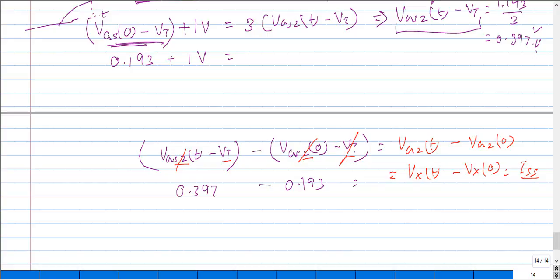And this quantity is basically assumed to be equal to the slew rate, and that is given by ISS divided by the capacitor C2, times the time that we have, and this is the time that we are expecting. That is the calculation that we wanted to do: how long it took for ID2 to reach 0.1 times ISS, right? So I know this quantity, substitute all of those values, and we would end up with time equals 102.3 picoseconds, and that is as simple as that.